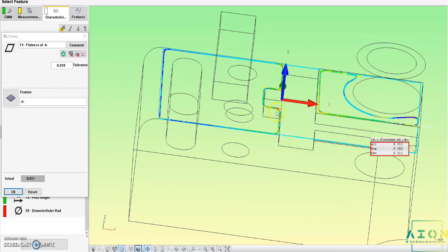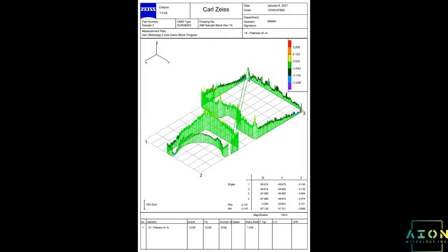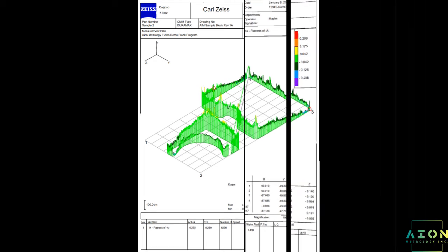When working with cast or molded parts, knowing the shape of your part can be very helpful in understanding why the part is not flat. Is it curved, wavy, bowed? Does it have sunken or swollen areas? These are questions that are answered quickly with a visual, helping reduce downtime while problem solving.